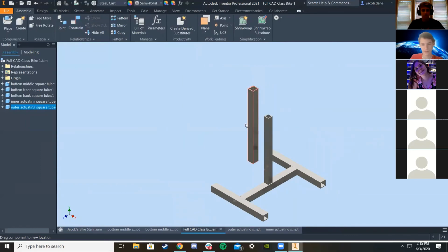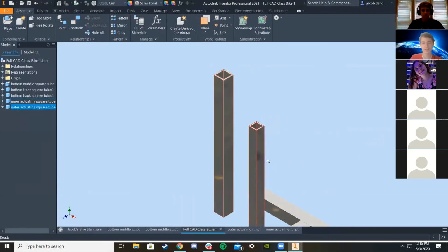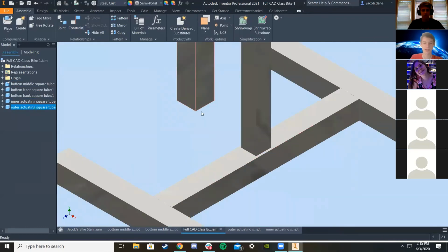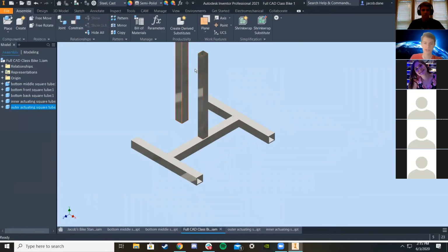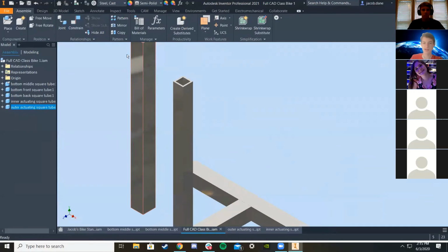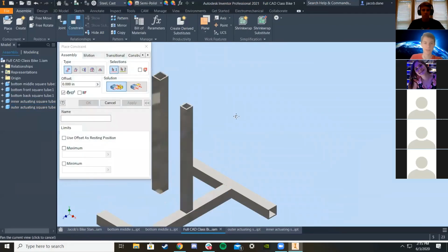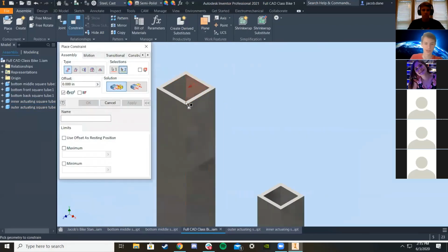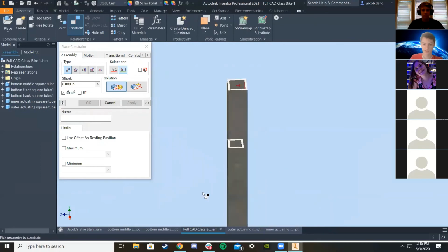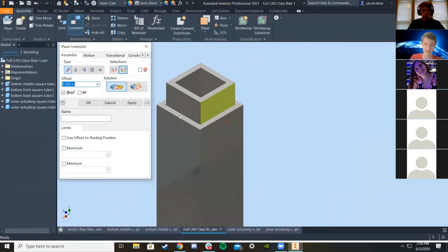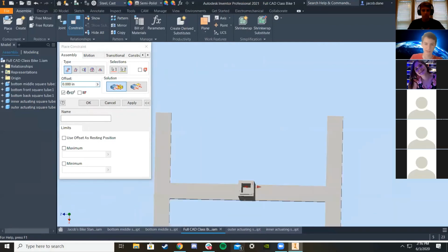In this one, okay, I think I'm just gonna do this. So I'm not gonna constrain this to this tube because as you remember earlier, instead of actually no, I'm lying. I'm actually gonna do that. But remember, I can't just do a simple constraint from this face to this face because, okay, you can't tell from here, but we had that little tolerance.